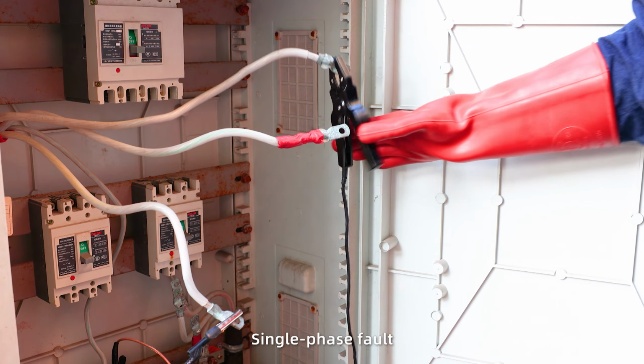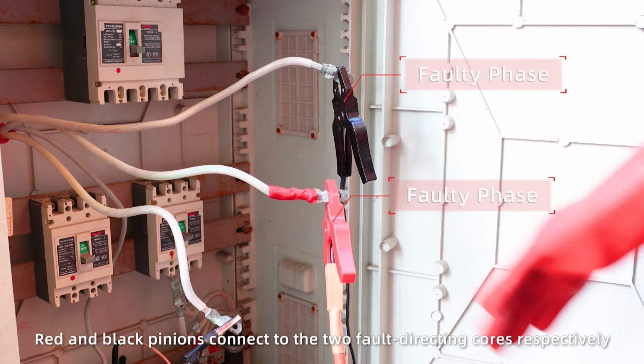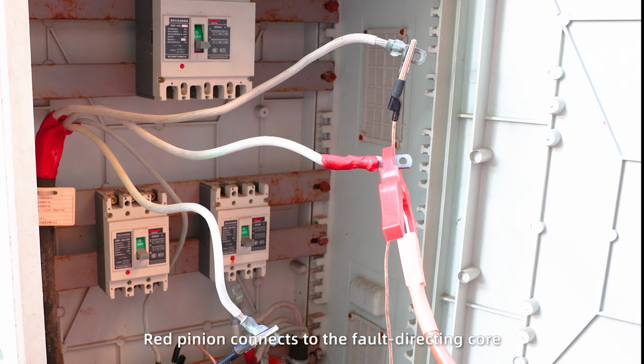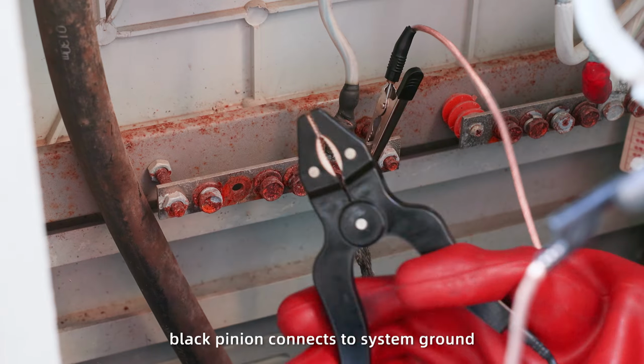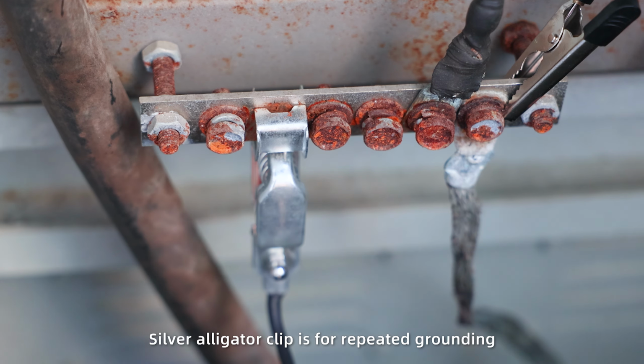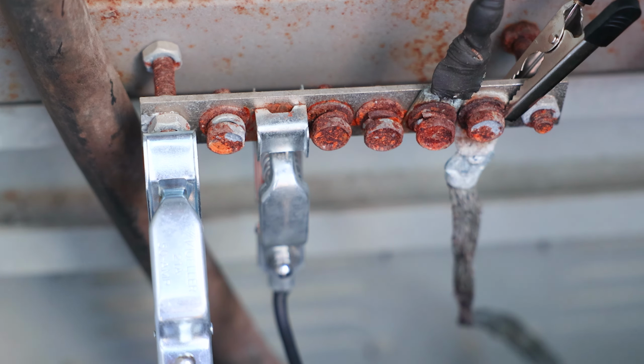Single phase fault: the red and black clips connect to the two faulty cores respectively. Single direction fault: the red clip connects to the faulty core. The black clip connects to system ground. The silver alligator clip is for repeated grounding, connected to system ground.